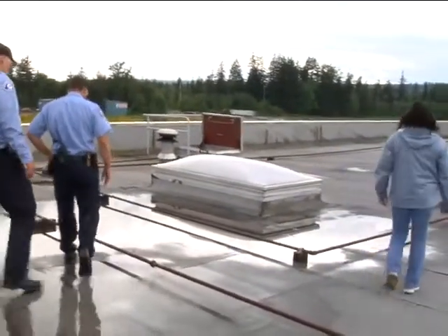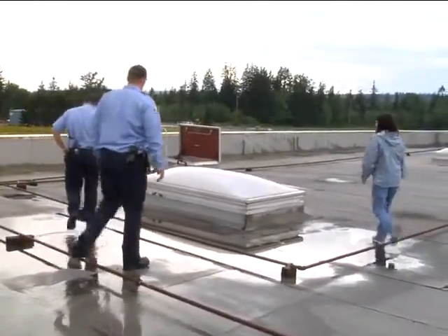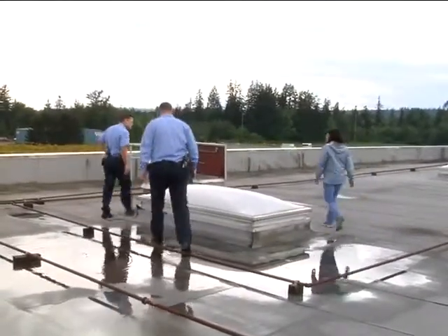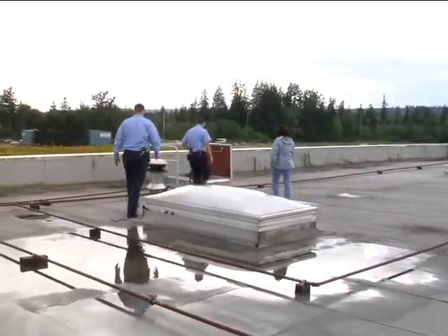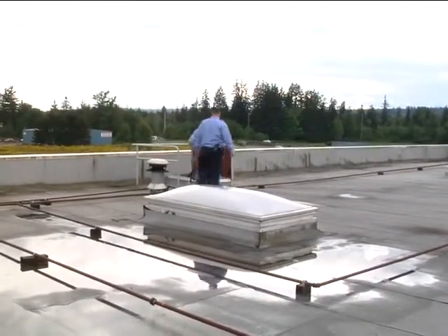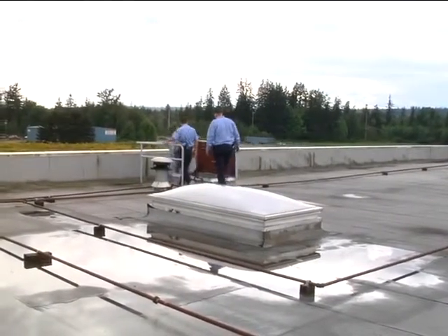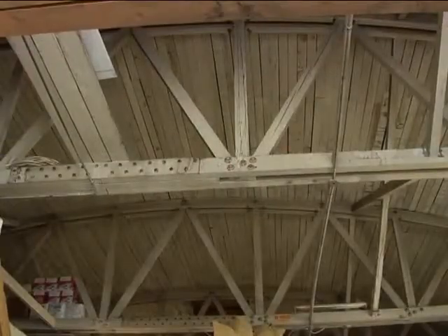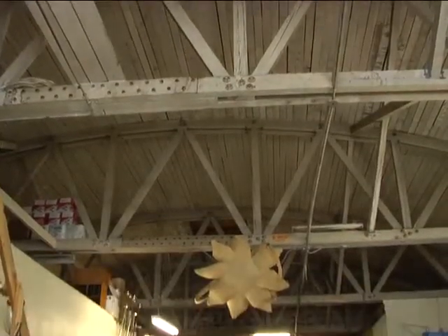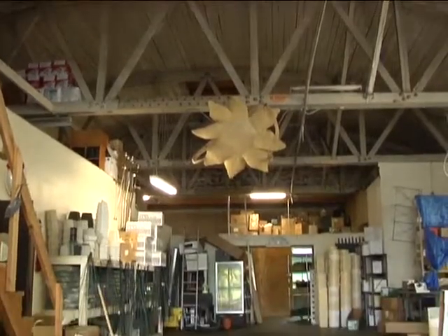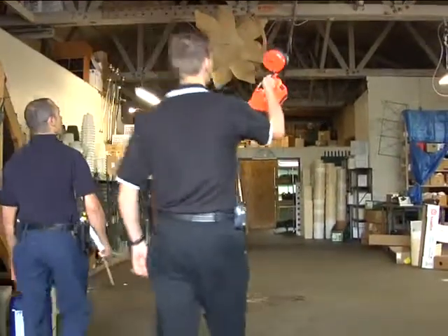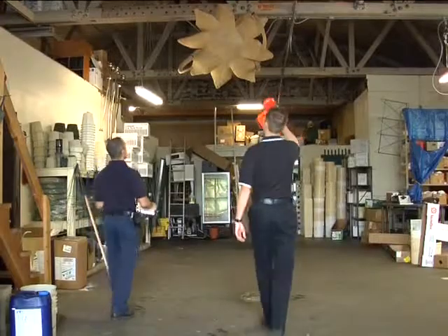Gypsum boards, about 2 inches or 50 millimeters thick, may be installed directly to the metal trusses instead of the wood sheathing. You would only know this by conducting inspection surveys before an emergency occurs. The third type of roof is the arched or curved roof, often found on warehouses, supermarkets, and bowling alleys. They're distinguished by the arched shape seen from outside. Like flat roofs, arched roofs have a cockloft, through which fire and heat can spread rapidly, weakening the roof.